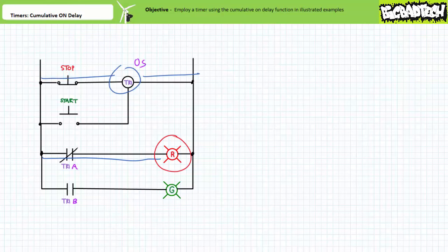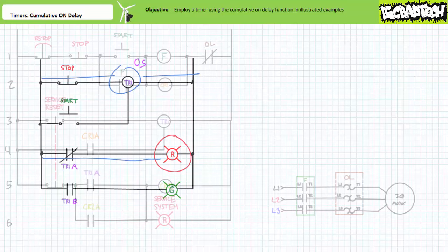When power is restored to the timer by closure of the stop button, the cumulative on-delay begins anew and the accumulator is reset to 0 seconds. Opening stop therefore serves to reset an ongoing cumulative on-delay and clear the accumulator.